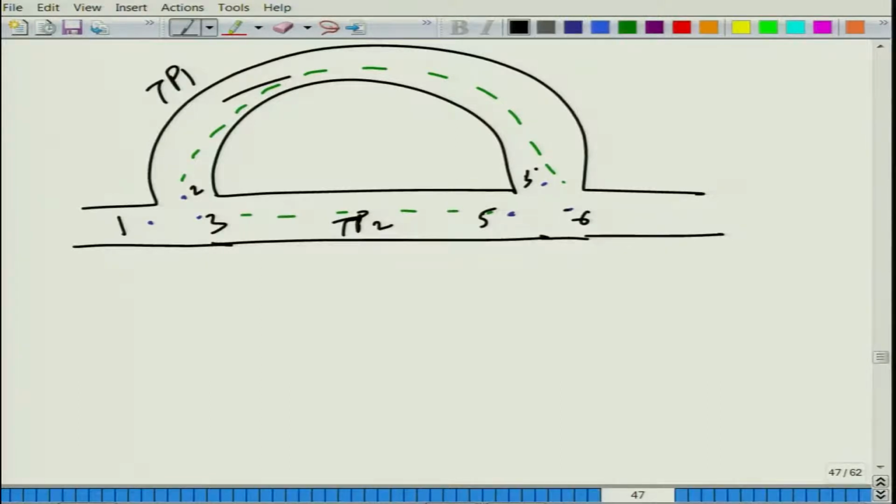So, what we will do is equate the pressures at this point 1, 2, 3, where they have come together at a very small point: P1, P2, P3 tilde, they are all the same. So, these are junction laws. Junctions are really points where two or more elements are connected together. Those elements themselves can be a 2-port element or a multi-port element, we will soon figure out, depending on the network involved.